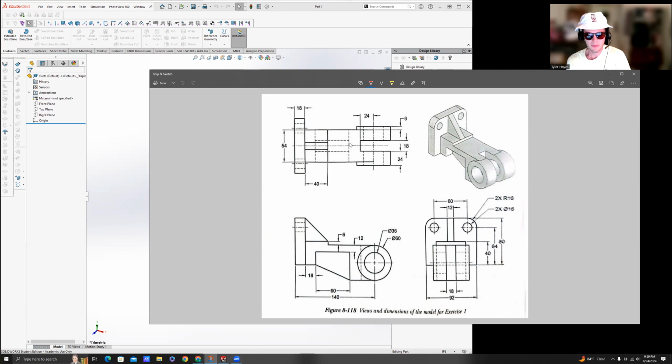Another thing I'm seeing here is there are a lot of these lines right here. They're called hidden lines. Basically, they're edges of the part that are projected through the part and into the view. Personally, I'm not a huge fan of them, not my artistic choice, but they are legal. They follow ANSI standards and whatnot. But personally, when I do the drawing, I probably won't do that.